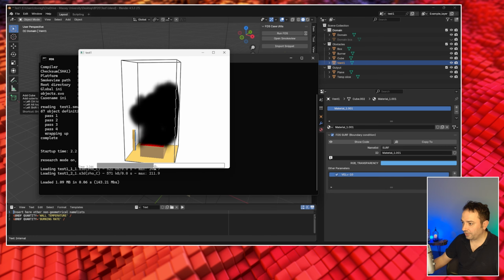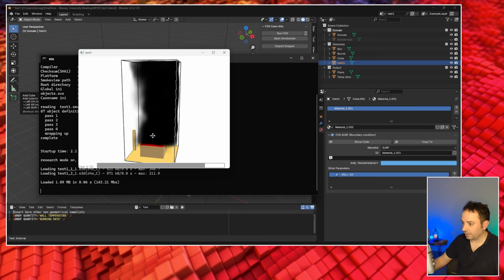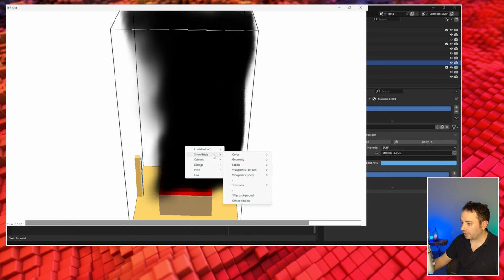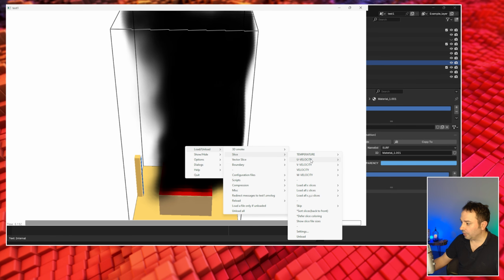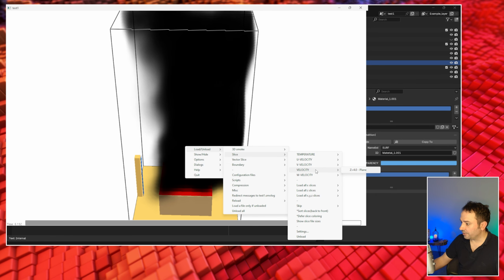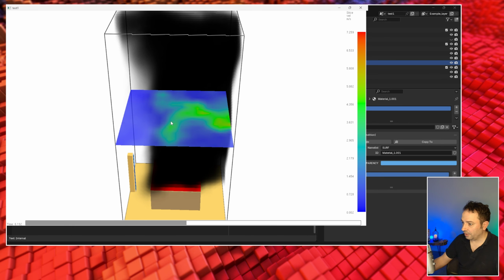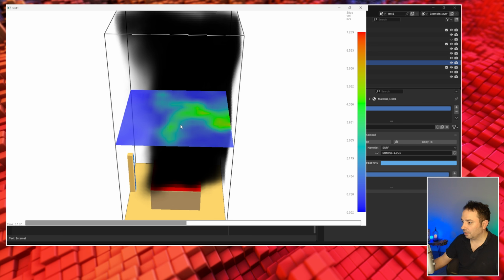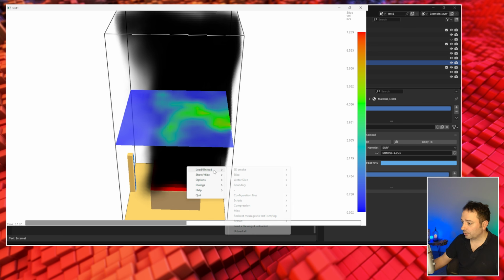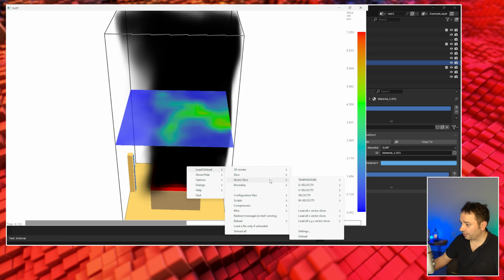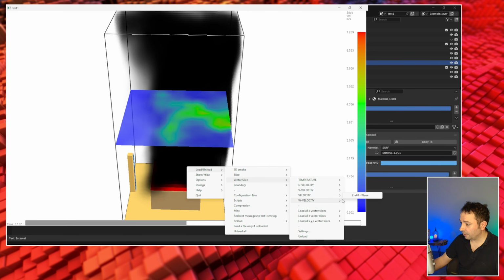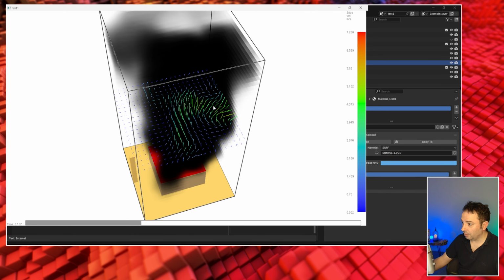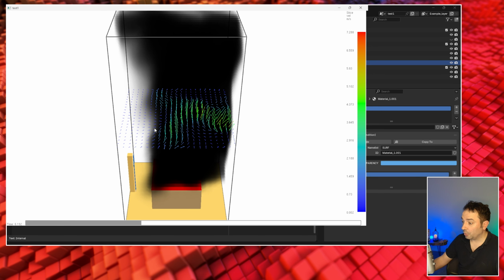So let's go and see Smokeview with this new parameter for the vent and see what happened. So you can see that now the impact is much more evident and the impact of the wind is there. We can go even and have a look at the slice that we located before. So we can go and see the velocity and see that basically the impact of the wind speeding up and pushing the smoke in one direction. So we can go and see also the vector slice. If we go here, you can see that the impact of the new vent pushing the smoke in one direction.